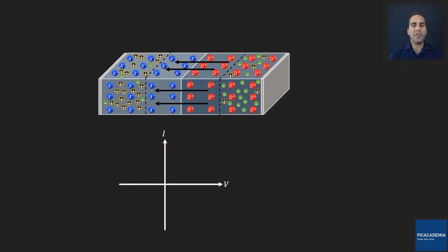In the lecture covering photodetectors, you saw this PN junction. We were interested in photons to cause generation in the depletion region. If you watched that lecture, you already know what I'm talking about, and if you haven't watched it, I highly recommend you go back, watch it, and then come back to this lecture. If we look at the IV curve of this PN junction under no illumination, we'll get this blue curve, which is similar to any other diode we've seen in this lecture.